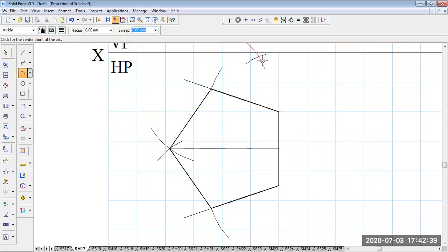Okay, now in the same fashion, draw the arcs on the other sides also. Now I'm going to draw an arc here, and again I'm going to draw an arc here. Now you can see we are going to get the 2 points. You can connect these 2 points properly, by which you are going to get the midpoint of this line. Now from this point you can connect it to the corner over here. Now this line we call the perpendicular bisector.